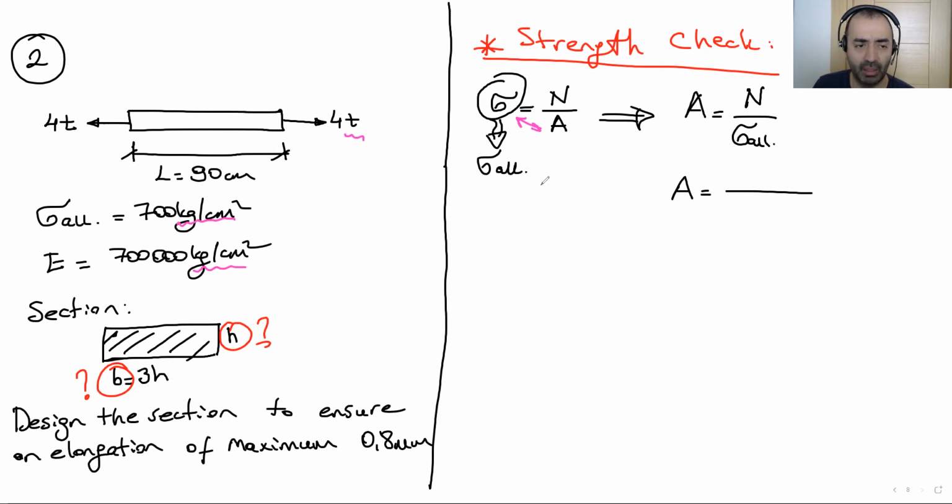By the way, in this type of calculation, if you're going to do a unit conversion, I always check the units of the allowable stress and E, the modulus of elasticity, and try to work in these units. That's better for you. At that time, you don't have to convert the allowable stress and the modulus of elasticity to another unit, so it reduces the mistake potential.